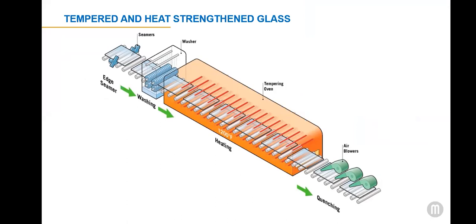Okay, and then another question came up. I ran into bullet resistant glass at a bank. Can you install film on that? It's really dependent upon what they're trying to do. If it's bullet resistant glass blocking the teller and it's not going to receive any solar exposure, you can install film on there, but you have to make sure that the surface you're applying to is actually glass. Sometimes they use polycarbonate or a different surface on the outside to control spalling, and you may not be able to apply film to it if it's not glass.